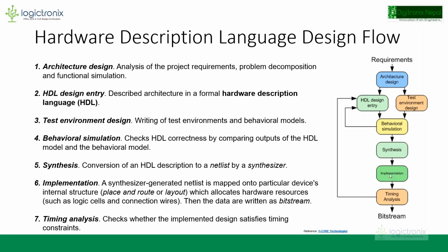The logical ports in the hardware description language programs, VHDL programs or Verilog programs, will be connected with the physical ones. Physical means the hardware-based ports. Basically, FPGAs have hardware-based ports. So physical ports will be connected with the logical ports. This is the process of implementation.